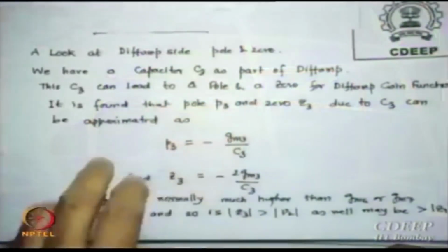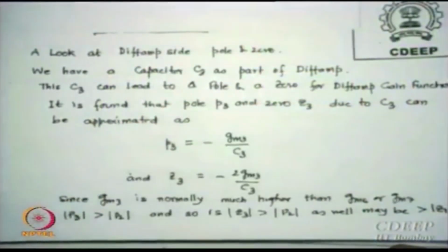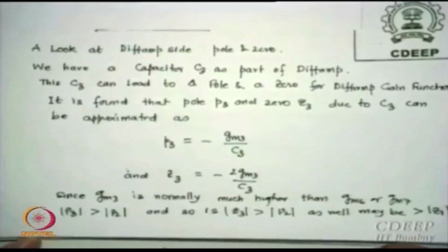Should I bring this here, should I place it on that same pole, so that I cancel it? Okay, Miller I don't want to increase CC, that I knew. If I increase it then I have more issues. So I said okay, CC I kept, now I bring this 0 onto the pole and cancel it, nulling the effect. So we will do that, but before the last slide I just want to show you that there is another P3 Z3 available, but in most cases we never bother about them. But as a designer I thought we must show you that yes, there is a pole and 0 which you must evaluate, and if it is extremely far away, forget it, okay, which will happen.